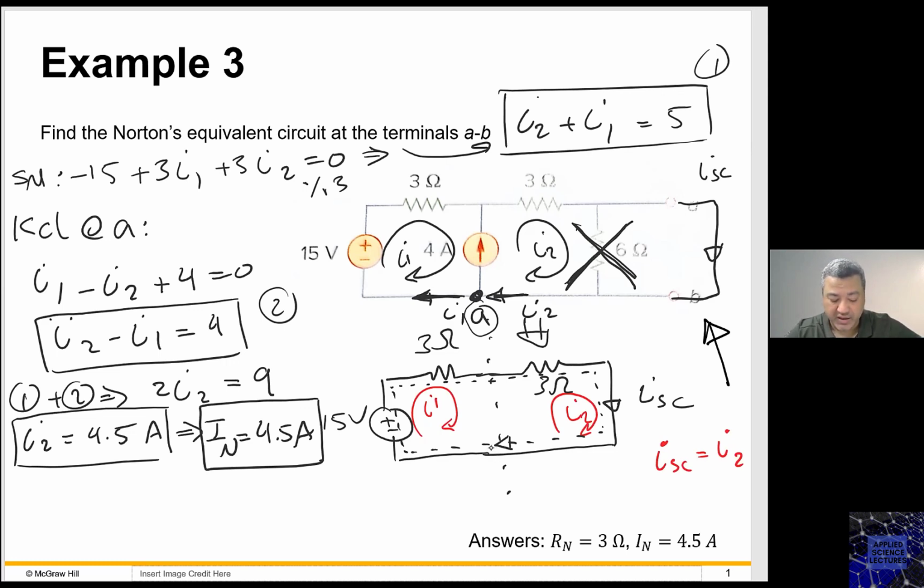So here in our case, we had a 6 ohm resistor that was shorted, and the circuit was simplified down to the following. If you recall, we had a current source here that we just removed for simplicity, but this current source has 4 amperes, and we drew this dashed loop, and we said that this now is my super mesh, and I assigned I1 and I2 to those two meshes that the super mesh is made of, and I wrote the super mesh equation